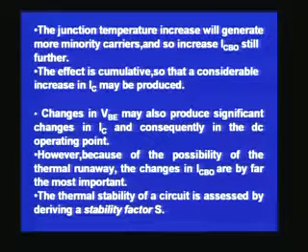Due to that you would find the collector current, because of the temperature variation, will start increasing without any control on its own, and after some time the current can become very large, and if you are not able to check this, it may ultimately lead to the transistor being spoilt. Due to the large current flowing through it, it will exceed the power rating of the transistor. So one has to be very careful. This is what is called thermal runaway. The transistor runs away with larger and larger current, initiated by the temperature variation, and the temperature variation increases IC, and IC increases temperature. So each one helps the other and they both run away, and finally we end up with the transistor getting spoilt. So we must make sure the thermal runaway condition is not generated in any amplifier. That is one of the very important things. That is why people say ICBO is a much more important parameter to worry about than the VBE.